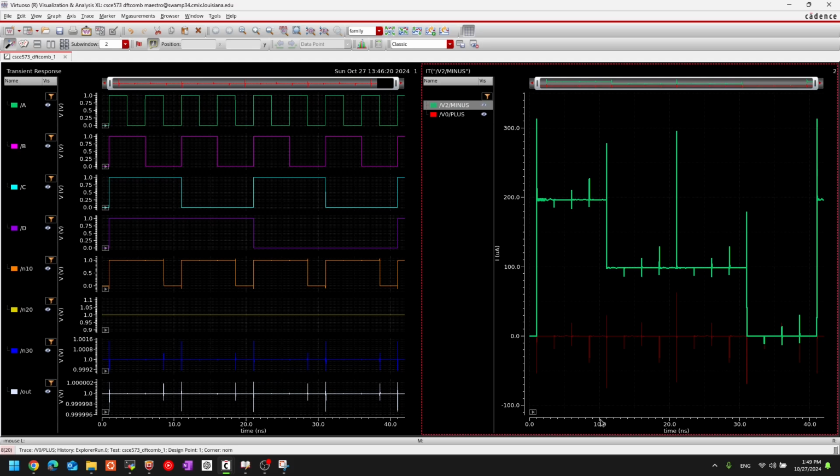And at the same time, between 11 and 21, or maybe, yeah, 11 till 31, you have a high steady state current, and your circuit is really consuming too much power. And this is really what tells us where the stuck-at faults are.